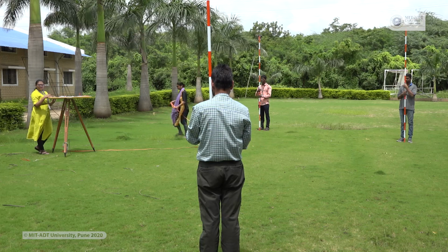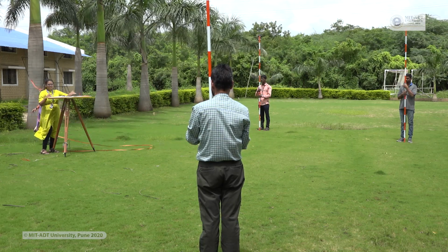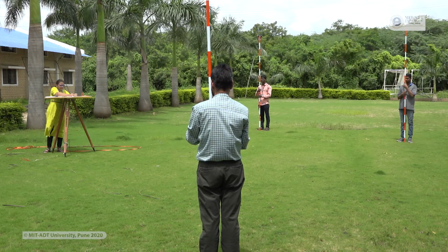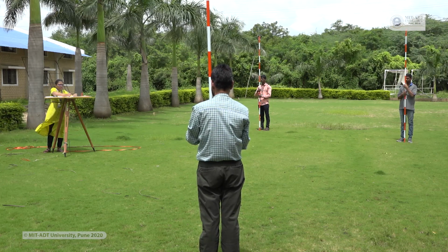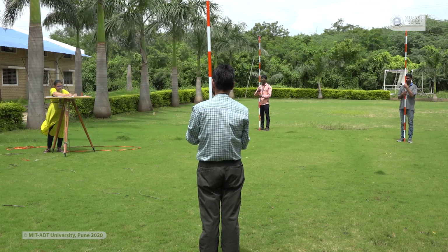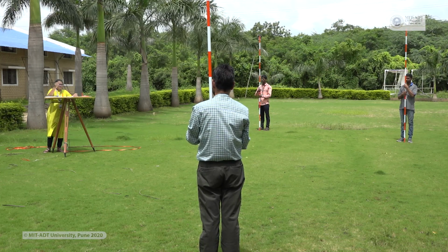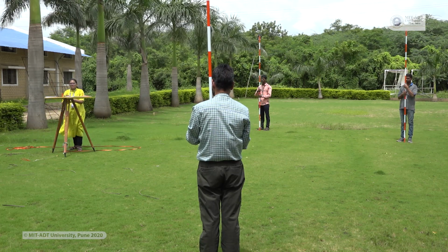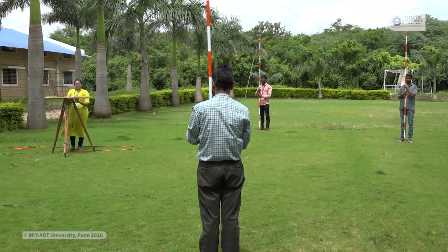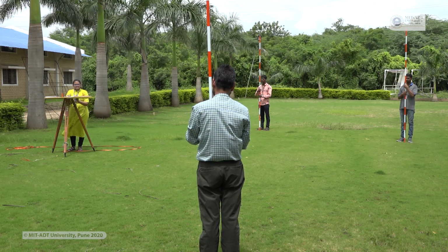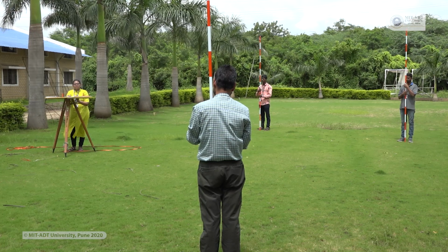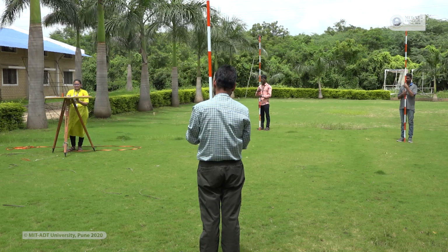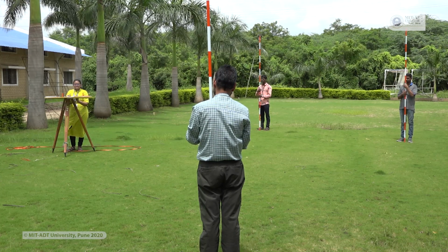So, I will just convert these 2 points into the scale and we will draw our object. So, my conversion I have made sure, then I have adjusted and I will draw a line between these 2 rays. So, in this way you can see that our 2 station points are marked onto the paper. So, this method is very useful when we have to bisect the objects which are inaccessible, and also we have to make sure that our ground measurements are correct. And if you convert the scale into the readings, then you can check our readings also.